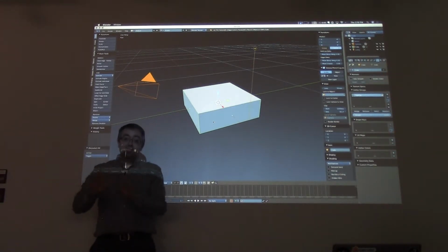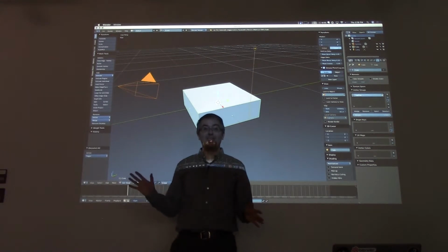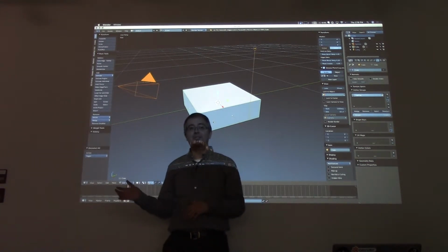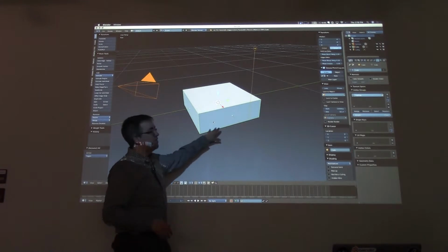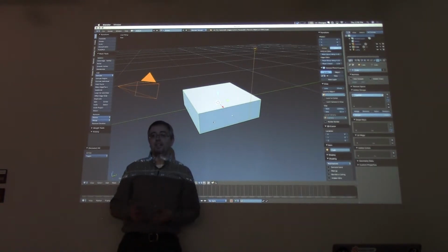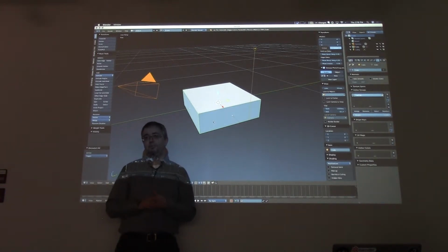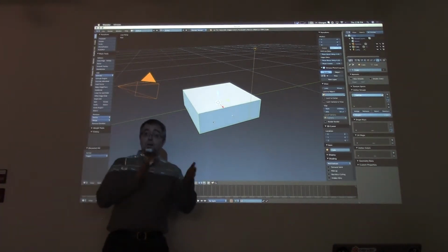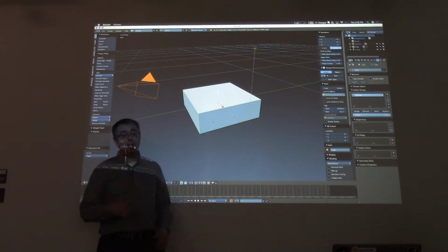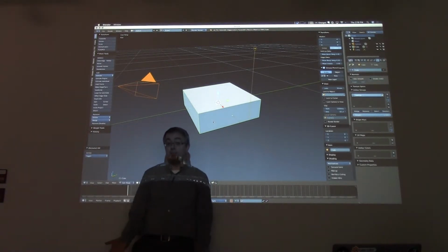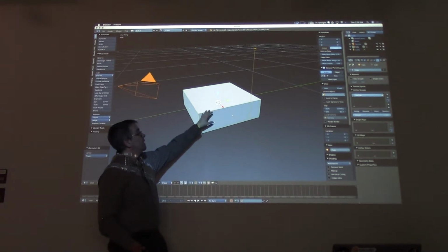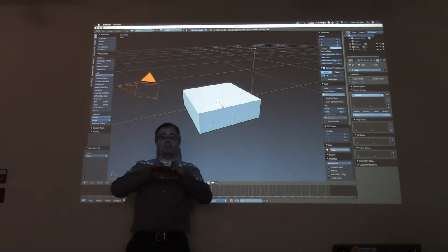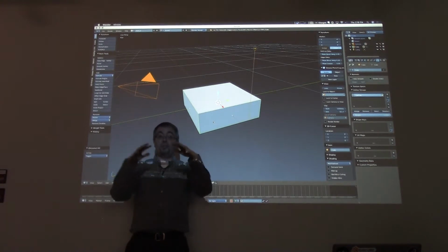And the reason I'm so afraid of extra geometry is that if I want to make other kinds of changes later, I want as few vertices to deal with as possible, right? That's the goal in modeling, the least number of vertices because that gives you the most amount of control. So instead of hitting subdivide a whole bunch of times to chop this up into pieces, note that the reason we're chopping it into pieces is that we want to make sure the object has enough parts to actually do the deformation.